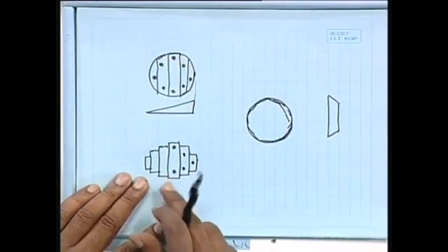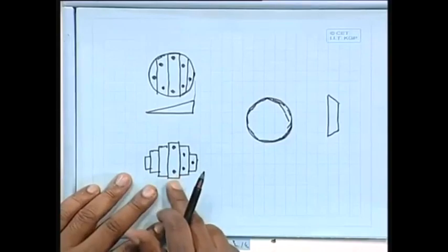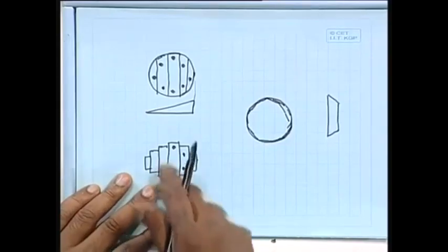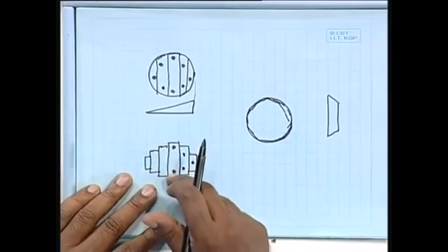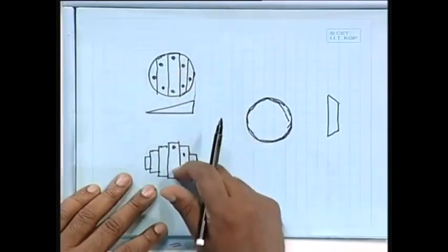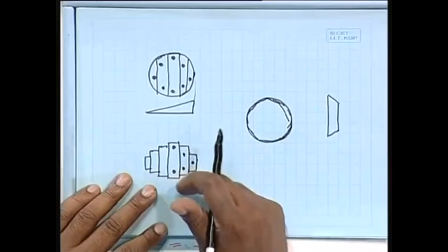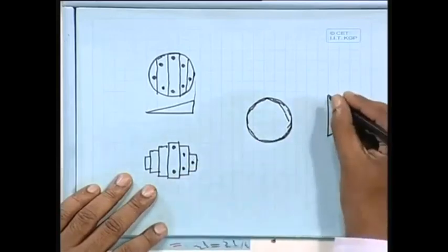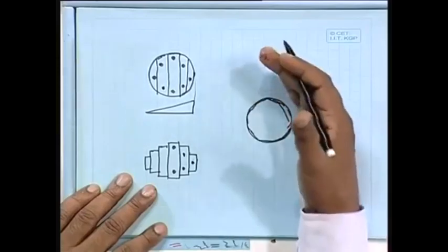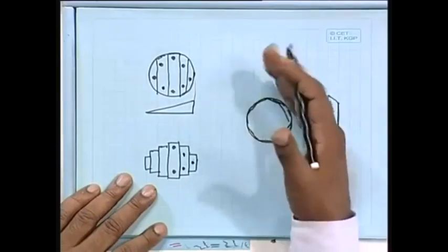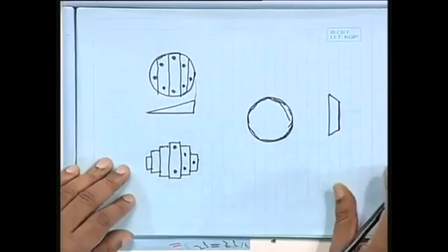That means in this case, if you can develop it for rectangular one, you can do it for the circular one also, that you are doing that equivalent section in this fashion. That means modeling the circular section in this fashion. Whereas if you would like to be a little bit more adventurous, then you can take your trapezoidal one, which will be more closer to your circular section. So this way you can make your own design.